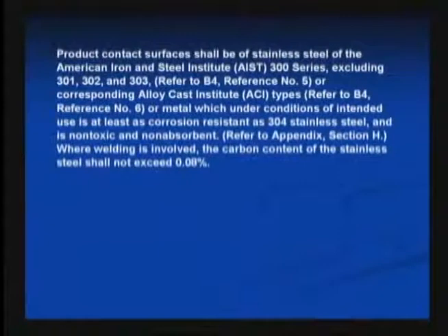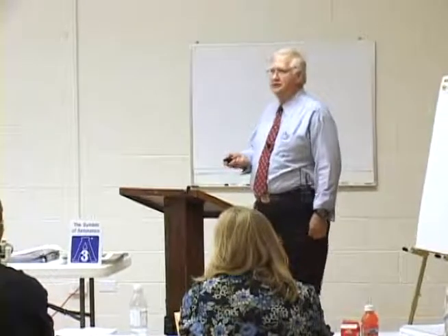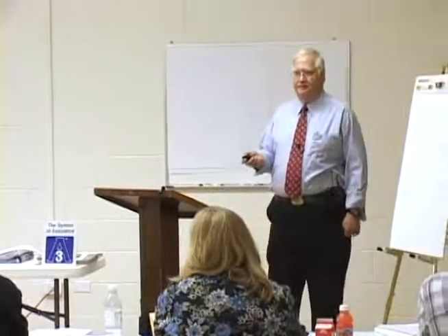Generally, the baseline requirement within 3A standards is 300 series stainless steel. That includes 301, 302, mostly 304s, 316 stainless.